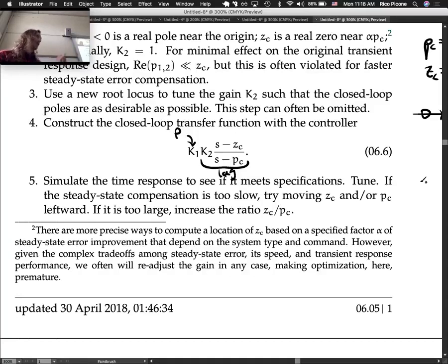So it'll give you resistors and capacitors and inductors, and you size them appropriately, and it will compute the error and then scale it by whatever your gains are for your controller, by the sizes of the capacitors and the resistors, and it'll put out a voltage that will probably need to be amplified to go into the motor.